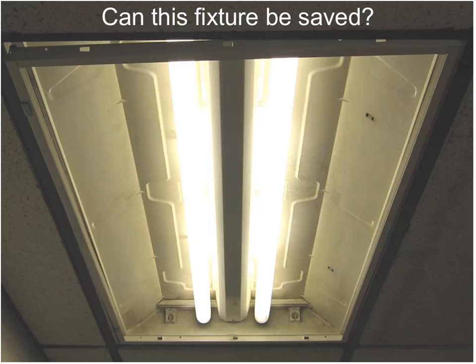So there's some clues here that are going to tell us what we might want to try and fix. If any of you want to indicate some areas of concern, feel free to do that. But I'm just going to jump right in here. First of all, you'll notice that we have an empty lamp holder. This fixture used to have 4 lamps, now it only has 2.